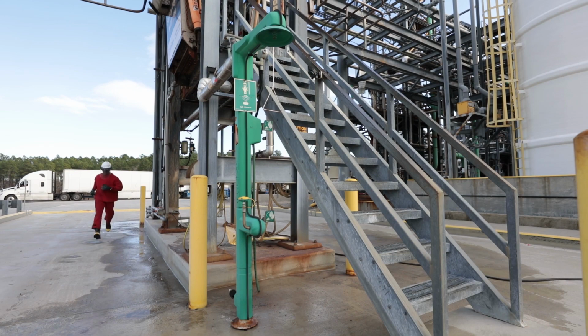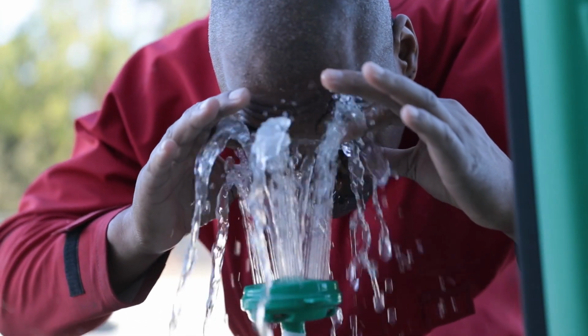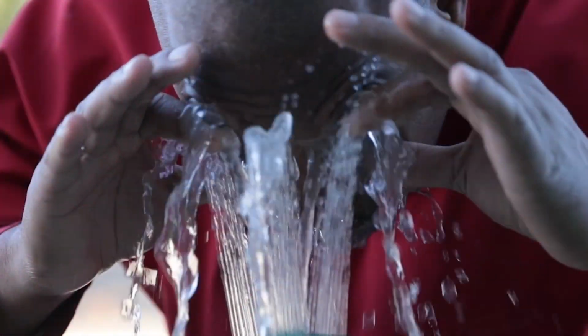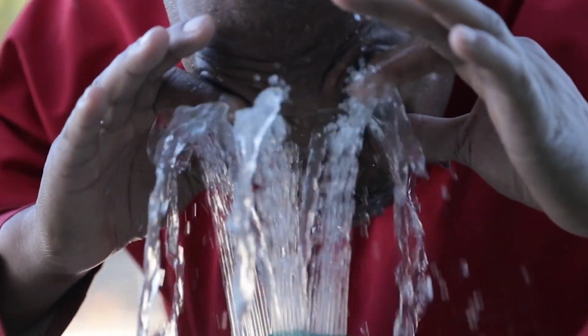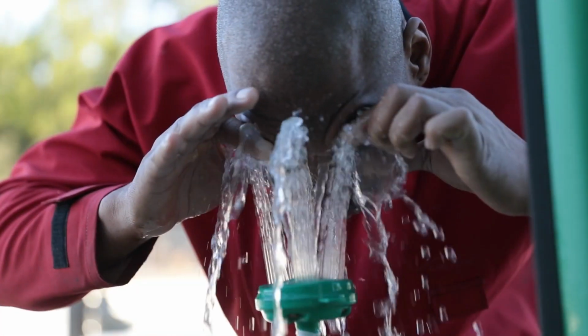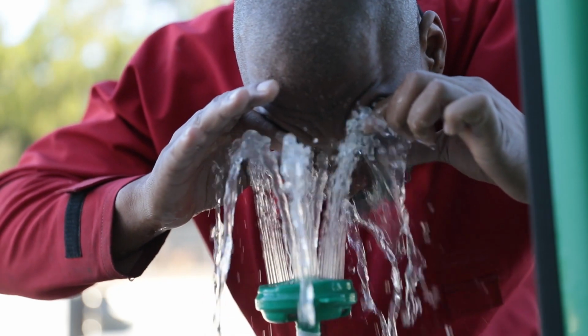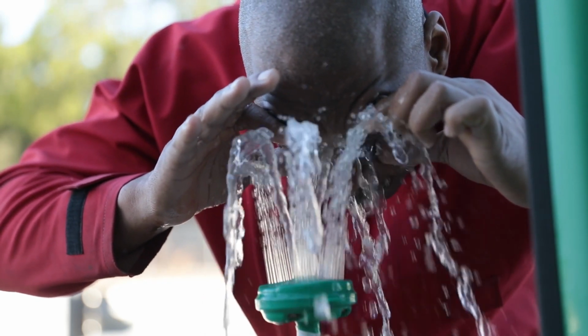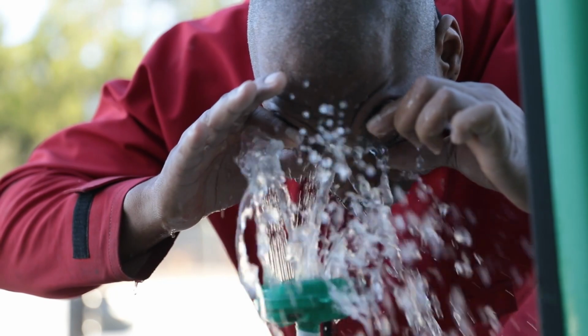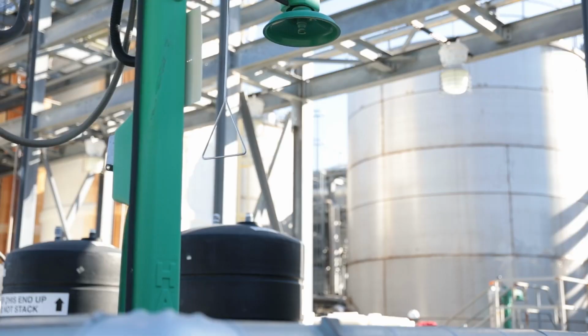If your eyes are exposed to a caustic solution, quickly get to an eye wash fountain. Every second counts. Begin flushing your eyes immediately. Once your hands are washed and free of any possible material, use your fingers to hold your eyelids open. This will allow water to flush any caustic solution that is inside the eyelids. Rinse your eyes uninterrupted for at least 15 minutes and then continue washing until directed to stop by responding medical personnel.